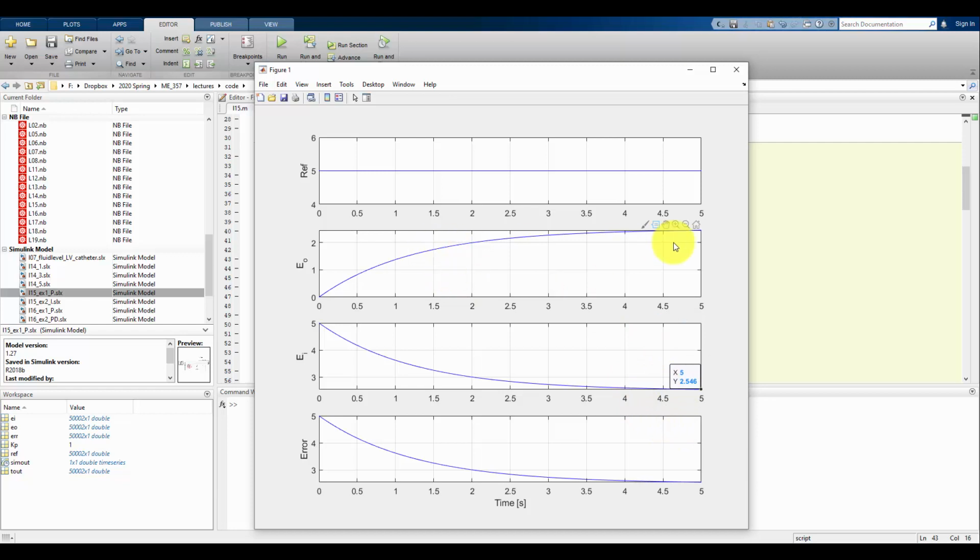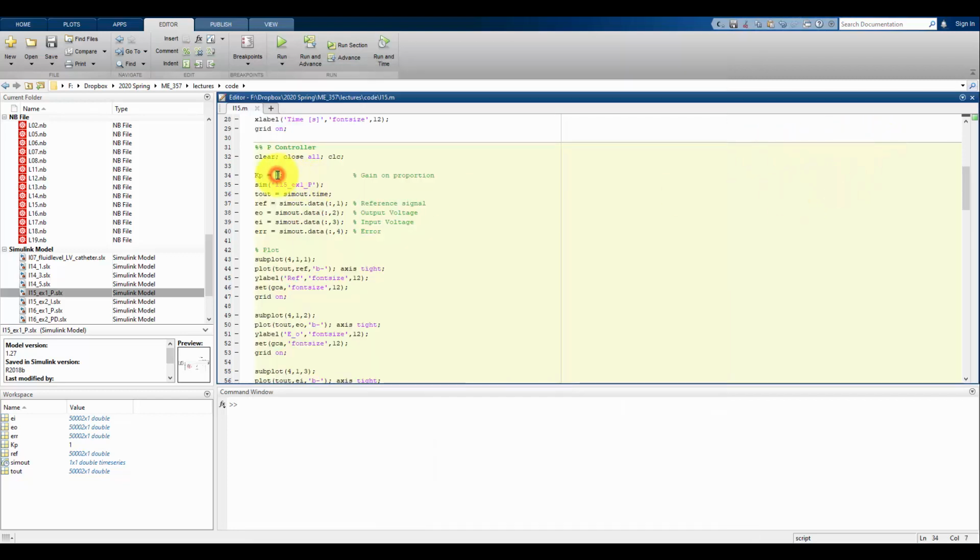And last part, we can look at the E out again. It is a first order system. Our closed loop system is first order. So if we look at where the time constant is, that's going to be determining the response time. This one is going to be slower to respond than subsequent tests we do, and we'll compare all 3 examples at once in the end. So quickly, we'll see the difference. What if our gain is 2 instead of 1?